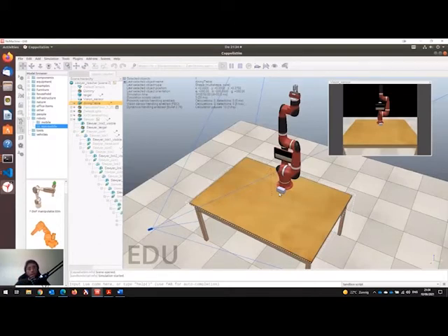So it always gave me an error that basically said that the distance between the gripper and the target object itself was too big, which resulted in a non-return from the inverse kinematic module, because there are no configurations, which is logical.